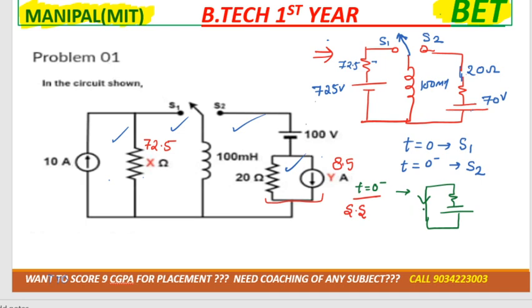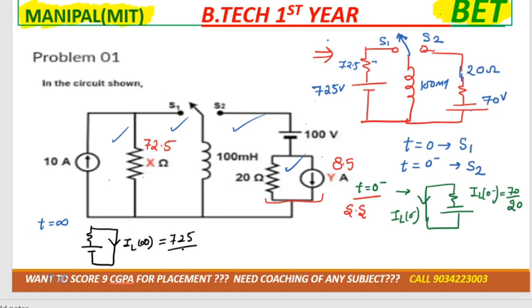So the current flowing across it would be IL of 0 minus. In this case, how much is IL of 0 minus? IL of 0 minus is V by R, that would be 70 by 20. Okay? Then after that, we need to calculate similarly for t equal to infinity. At t equal to infinity, the switch is connected to S1. Again we need to calculate IL of infinity, that would be V by R, 725 divided by 72.5, that would be how much? 10 ampere.